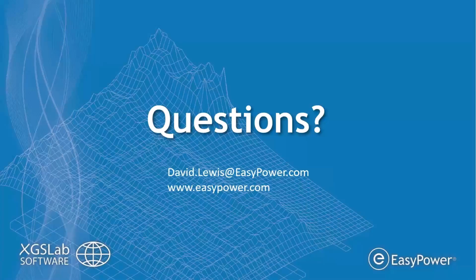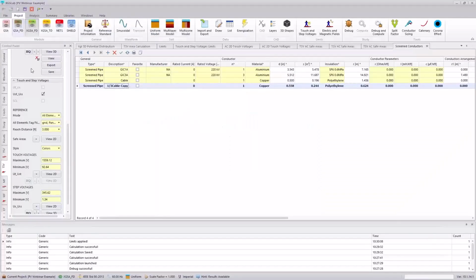Understanding these concepts is going to help drive that. But for some systems, there are going to be dramatic soil resistivity changes, and in those, you might break your system out into different regional analyses with different soil models to account for that. And with XGSLab, there are different soil modeling capabilities, like multi-zone soil modeling, that can allow you to account for the soil resistivity across the Earth's surface.